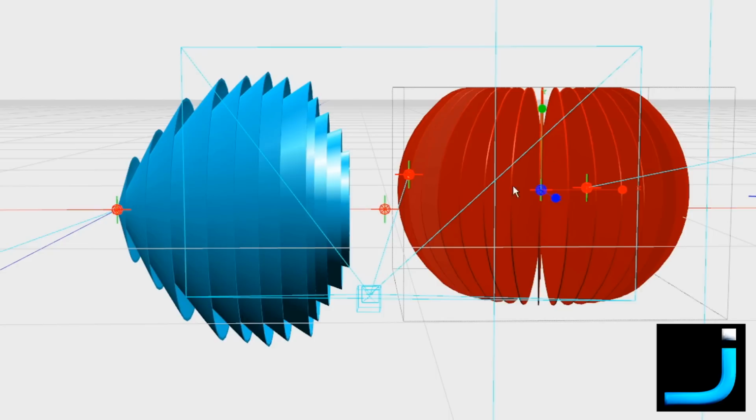One's circular, one's vertical. However, the great thing about a circularly polarized antenna is that your loss, instead of it being 26 decibel, remember, if you've got a horizontal antenna trying to talk to a vertical antenna, you've got a 26 dB loss, which is massive. However, the linear, as in vertical or horizontal polarization, versus a circular mismatch, is only 3 decibel.